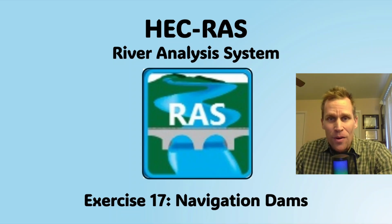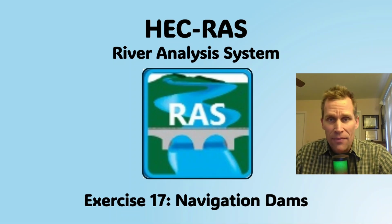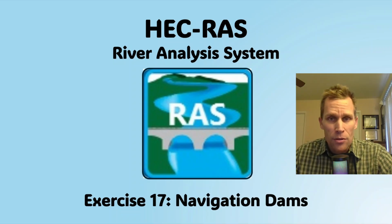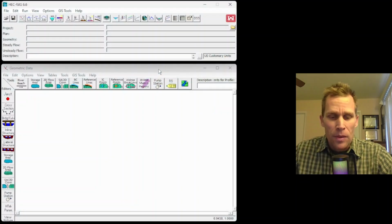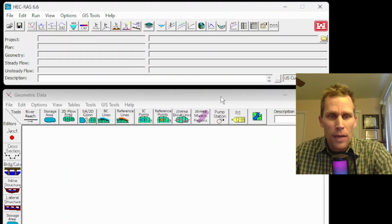Welcome and hello. This is a video exercise in HEC-RAS, and in this exercise we are going to be dealing with navigation dams. Navigation dams is a boundary condition that's available for inline structures, and it allows the model to regulate the water surface elevation either at the inline structure or further upstream.